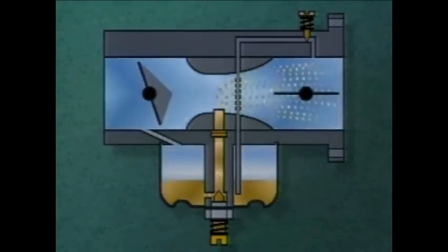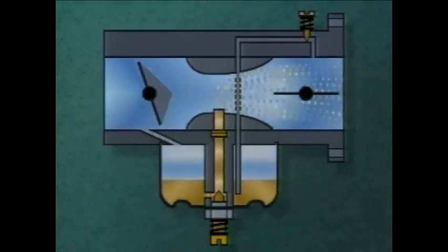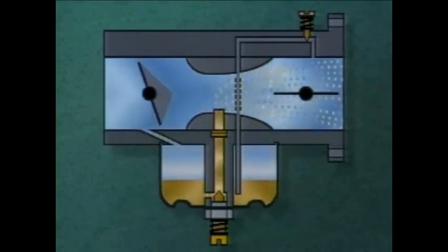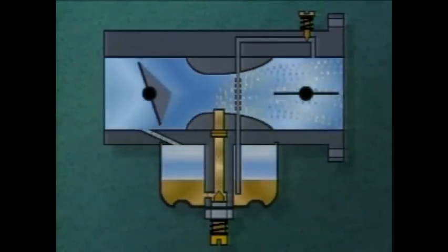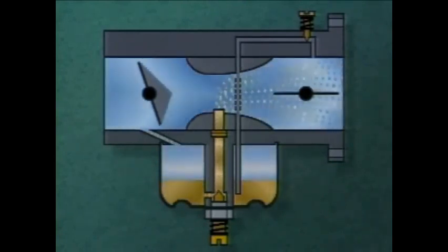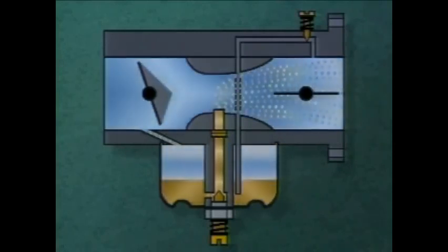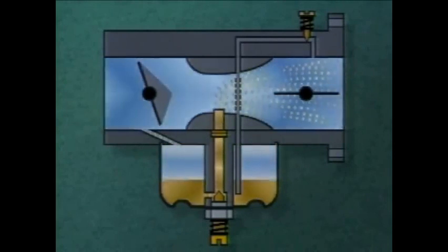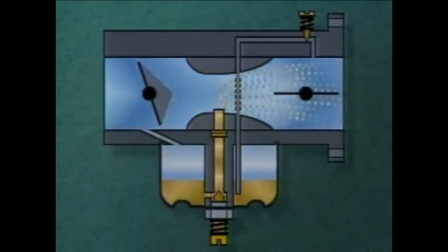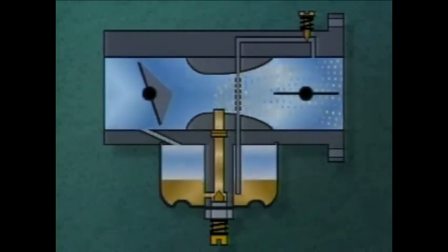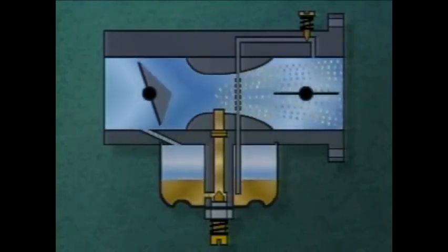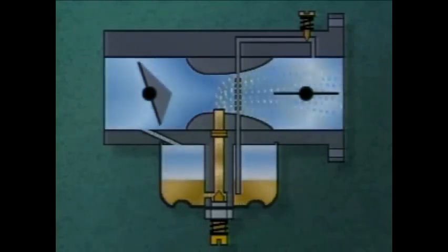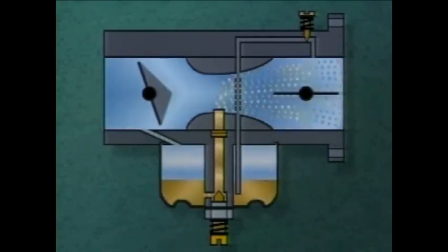When the choke plate is closed, it simply blocks or restricts airflow through the carburetor. Keep in mind that every time the piston moves down in the cylinder bore, it creates a vacuum that the high pressure surrounding the engine will try to fill. By restricting the flow of air at the front of the carburetor, a low pressure area is created throughout the carburetor behind the choke plate. The higher atmospheric pressure then pushes fuel into the airstream from the high-speed system, which creates a very rich fuel